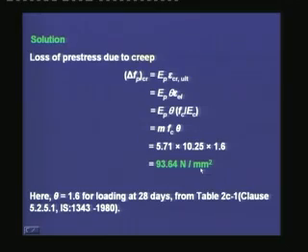This is the long-term loss of pre-stress after a substantial time, say after 5 years, and this can be considered to be the loss due to creep strain alone.